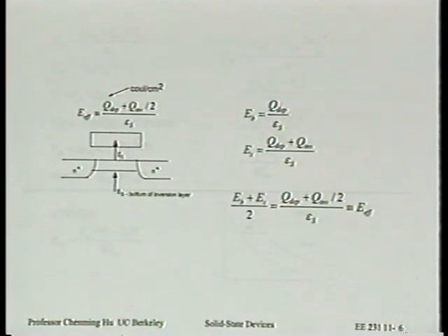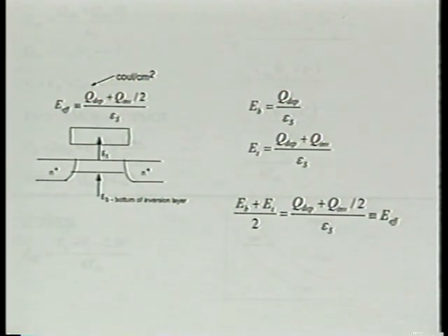But I did say that there are exceptions. The exception is strong nitridation. When the surface is not SiO2, then the mobility would be different. Okay, and that certainly opens a lot of questions about future different dielectrics, high-K dielectrics. What if it's not SiO2? What can we expect? What's in store for us? And you cannot answer those questions until you have some reasonable understanding of the SiO2 system.